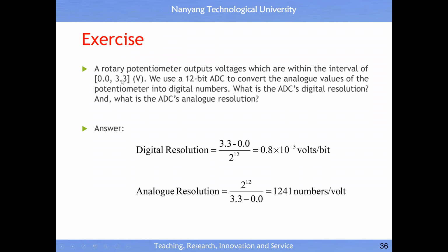If your sensor does not output the voltage in this range, you can always design a small circuit, either to scale up or scale down into this range. So that is not the issue. To scale up or scale down an analog voltage, you just use a network of resistors, done already, quite straightforward, right?